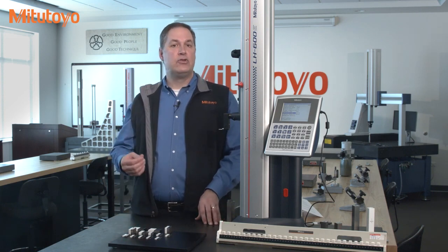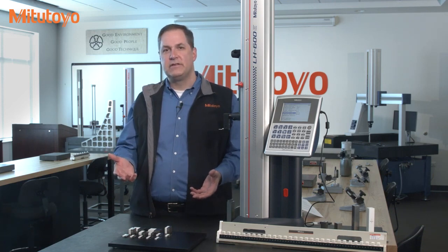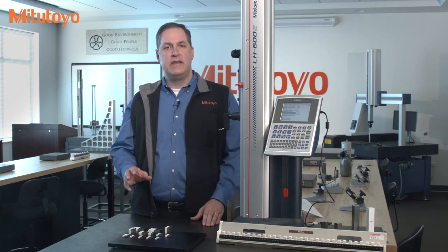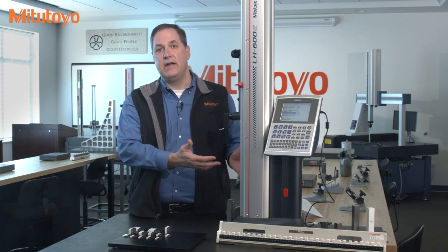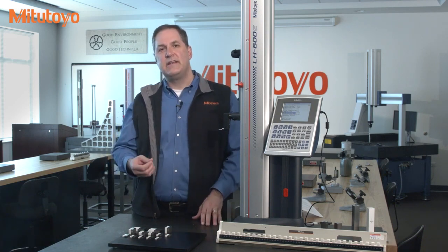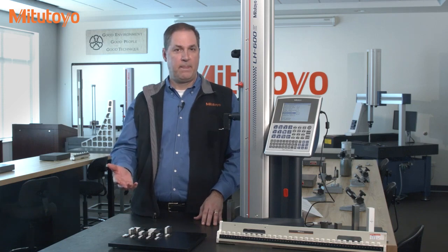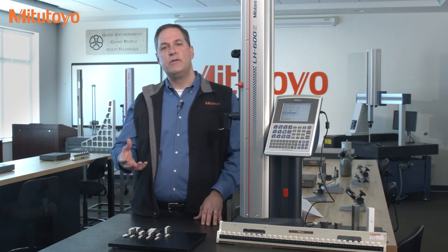In dimensional calibration labs, you may find environmental control at, say, around 18 to 22 degrees Celsius. And if you're just calibrating small micrometers and calipers, the thermal errors are usually small enough to not cause any concerns. But when you have longer measurements or higher accuracy equipment, something like this high accuracy linear height gauge, then temperature can suddenly be a big deal. So let's talk about some good practices to reduce the impact of temperature.